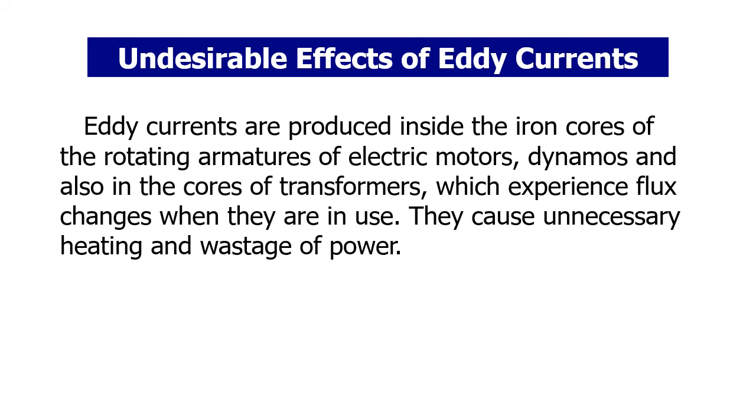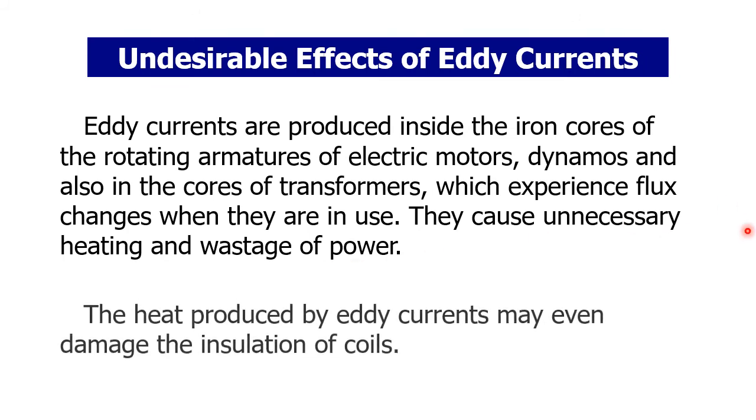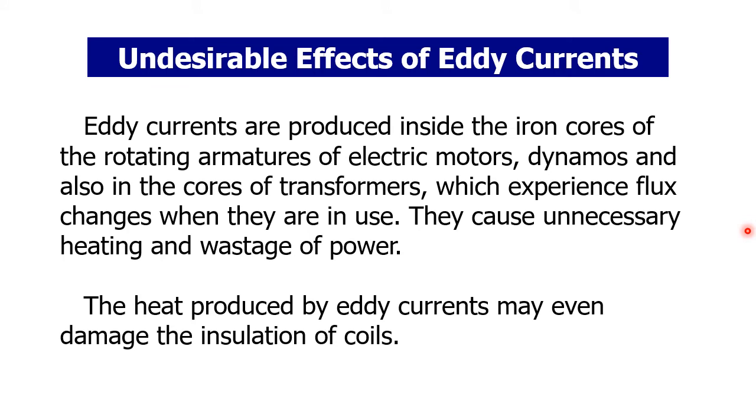Whenever eddy current comes, there is heat. I squared R amount of power is generating, that means heat. In the form of heat we are losing energy. If it is small, fine. But at a large scale, it causes unnecessary heating and wastage of power. In some cases the heat produced is high, and the eddy currents may even damage the insulation of coils. So there is damage due to eddy currents, but advantages are also there. It is like friction, a necessary evil. So here also, with eddy currents, there is an advantage if you can overcome the losses.